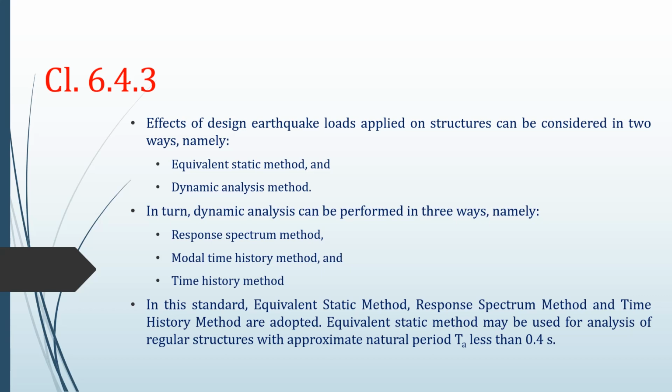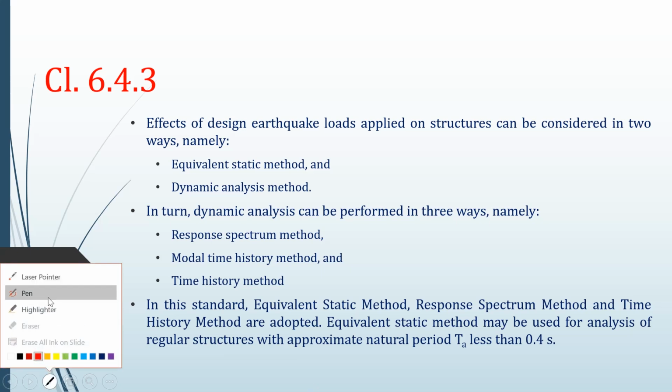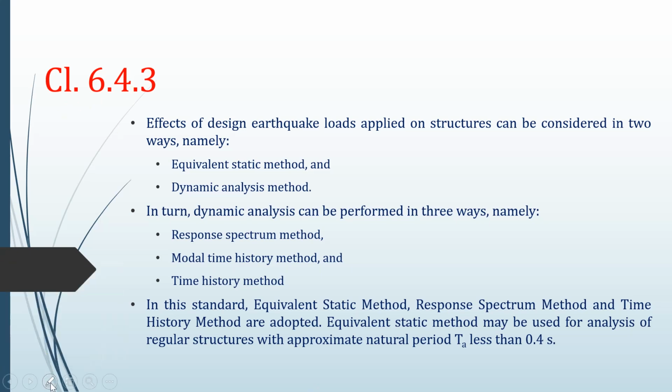Clause 6.4.3 of IS 1893 states that the effects of design earthquake loads applied on structures can be considered in two ways, namely equivalent static method and dynamic analysis method.